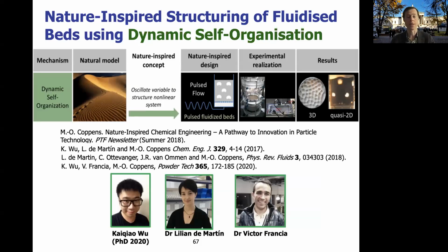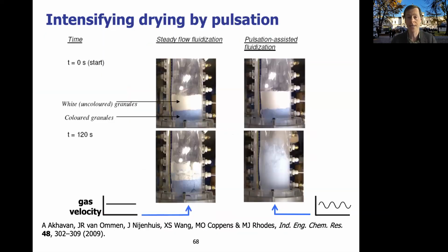Kai-Chia Wu is in our group. He just recently got his PhD, and former postdocs Linda Martin and Victor Francia. So when you oscillate the gas flow in a fluidized bed like this, and you have these problems of caking and blocking because powders are cohesive, you oscillate it, you can much more easily also mix the contents. So I kind of wanted to show you a few of these examples here.